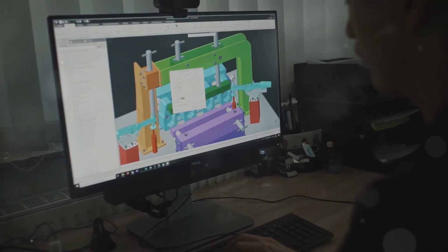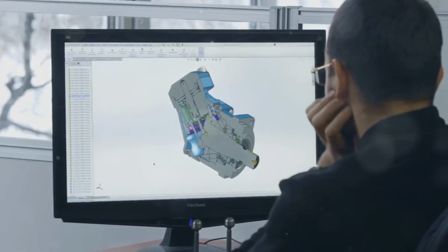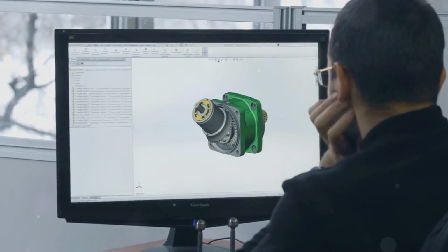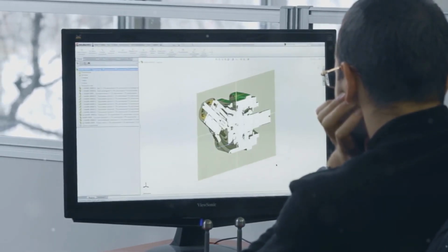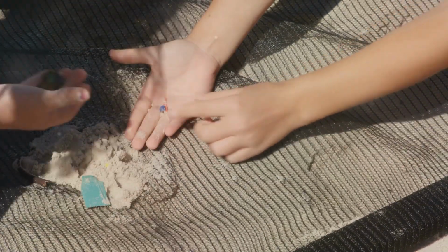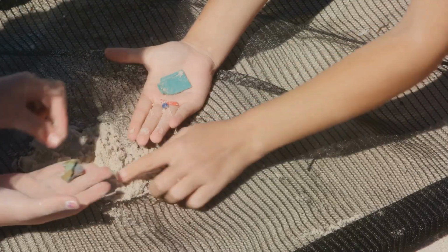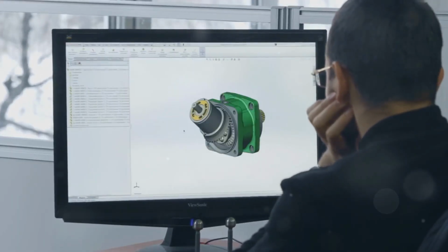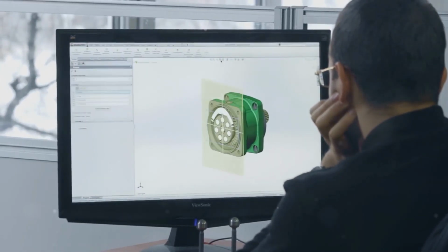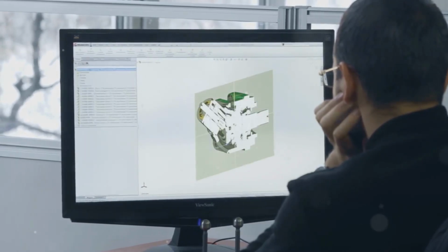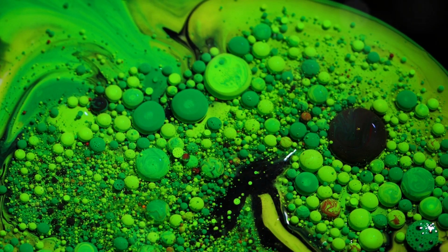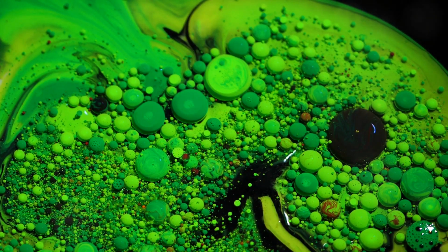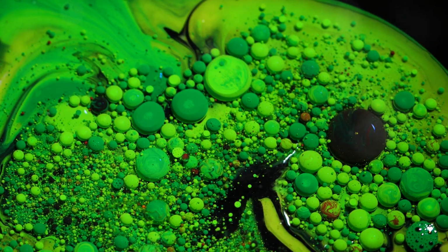The geometry defines the physical boundaries of the problem, while the mesh discretizes this geometry into smaller elements, forming the computational grid on which the governing equations are solved. The quality of both the geometry and mesh significantly impacts the accuracy and stability of the FSI simulation. For instance, a poorly defined geometry with sharp edges or gaps can lead to meshing errors and inaccurate results. Similarly, a coarse mesh with large elements may not capture the intricate details of the fluid flow and structural deformation, compromising the accuracy of the solution.